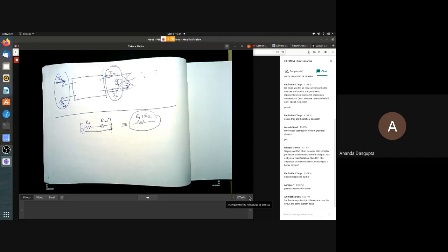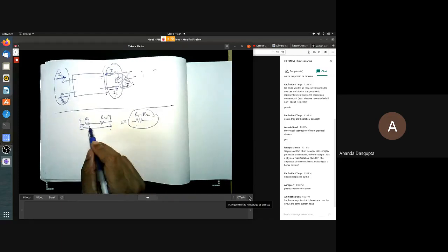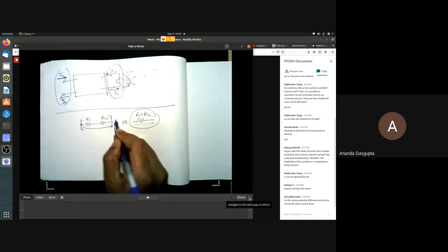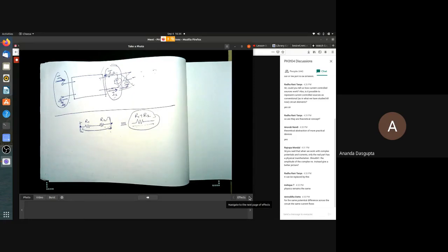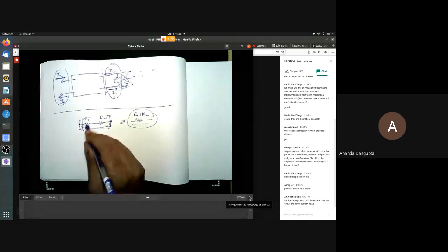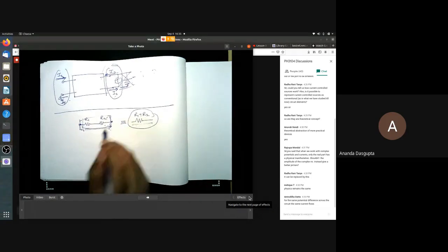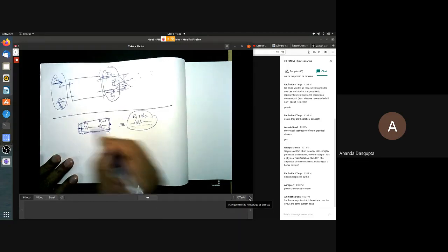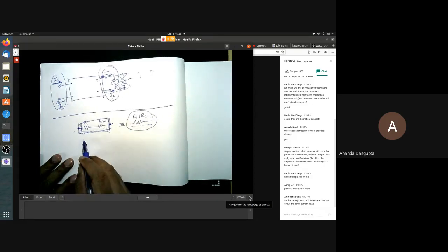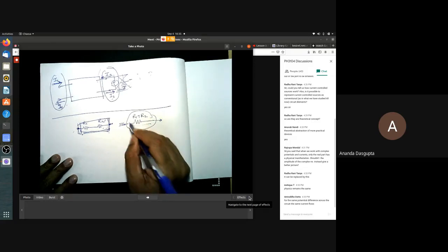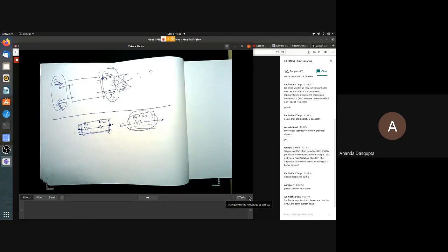Everywhere else is critical. Because, for example, the voltages here do not stay the same after you replace. The voltage difference across the two ends, which you should realize is actually outside this, right? Your R1, R2 combination speaks to the outside world through its two ends. So if you have understood the black box concept, you can think of putting this whole thing in a black box, two ends sticking out. If I were to change the inside of the black box and replace them by just this single resistance, by looking at it from the outside, I should not be able to tell the difference.